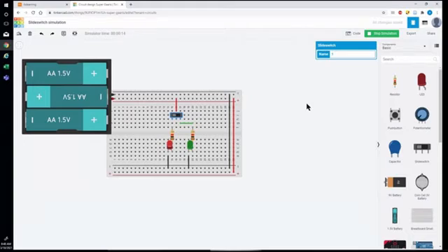But what if I want a little more? You know, this is not a real traffic light. This is like a pedestrian light, red and green, but the real traffic light has yellow. And I have only 2 terminals over here, so I only have 2 options for my red and green. I don't have the third option, but I can get a third option by using another slide switch.